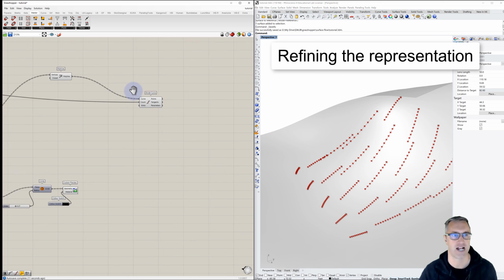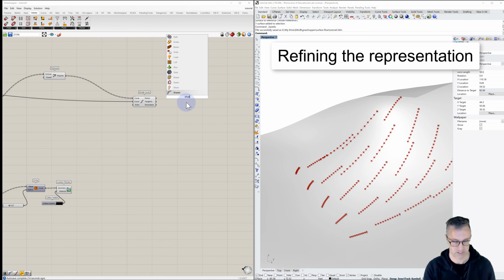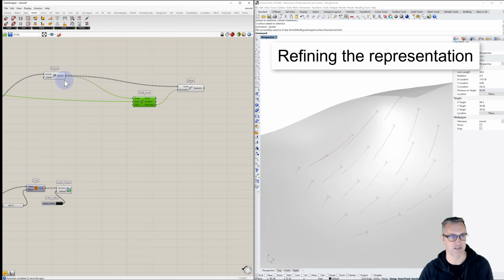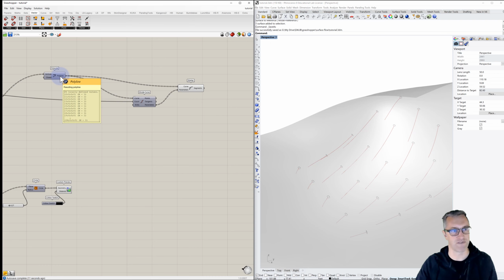And now let's shatter this curve. And basically shattering a curve breaks a polyline into multiple segments. So we're going to shatter our polyline, and the parameters that we'll use will come from the divide curve. We can hide both of these previous components. Looks no different now, but for when we had polyline earlier, we had 25. Now with the segments, we've got 250. Remember, we've got 25 lines, and then now we have 10 divisions along that length.